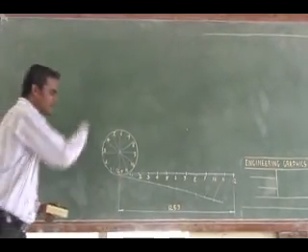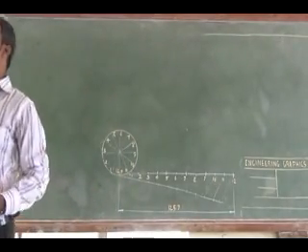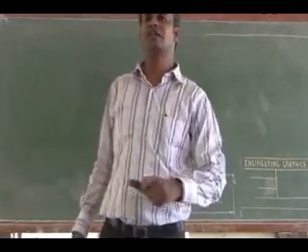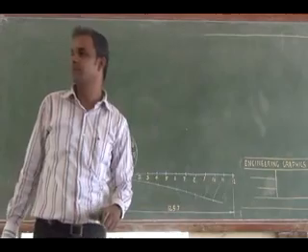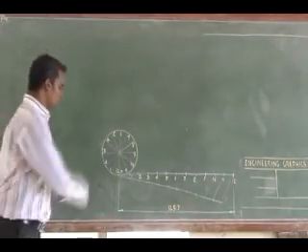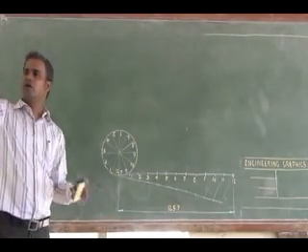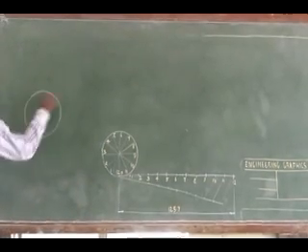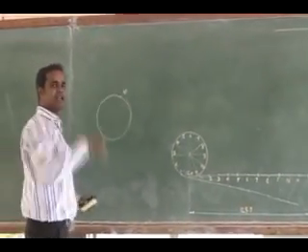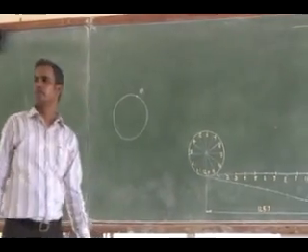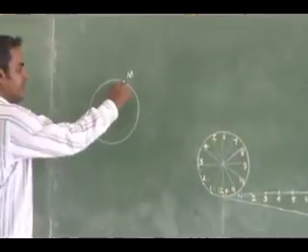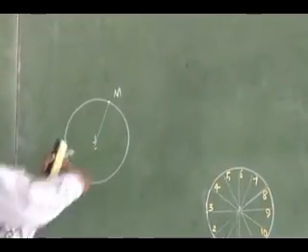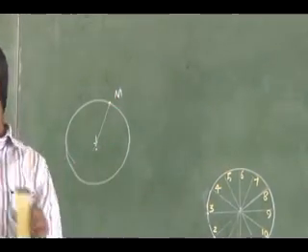So similarly for the 12 segments, on the 12 circumference points of the circle, I have to draw tangent lines. If I have a circle and a point, say M, how do I draw the tangent to it? Join M to the center, then draw a perpendicular to this line.